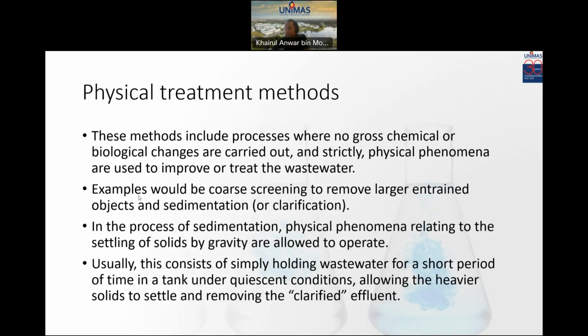The common examples are coarse screening to remove larger entrained objects, and sedimentation or clarification. In the process of sedimentation, physical phenomena relating to the settling of solids by gravity are allowed to operate. Usually, this consists of simply holding wastewater for a very short period of time in a tank under quiescent conditions, allowing the heavier solids to settle and removing the clarified effluent.